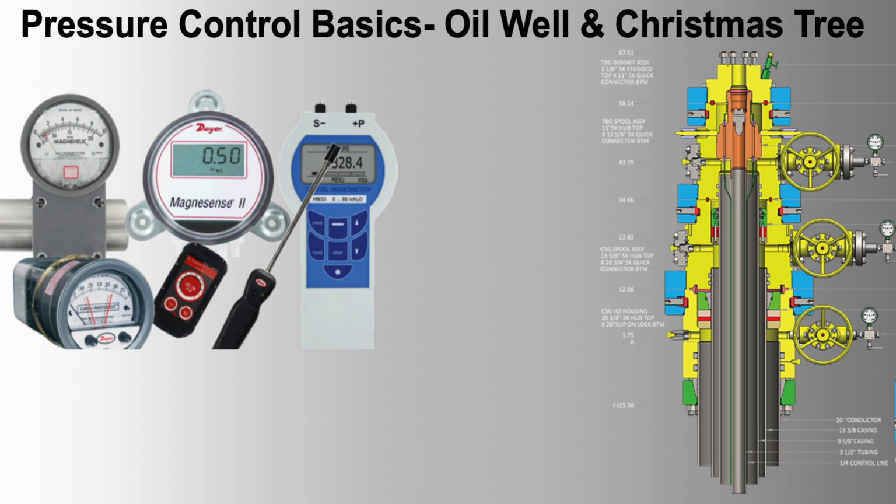Example issue 1. Instrument failure due to high temperature and pressure. Problem: standard pressure gauges failing at high temperatures and pressures. Solution: use quartz pressure gauges designed for high temperature and high pressure environments. These gauges provide reliable performance and accurate measurements under extreme conditions.